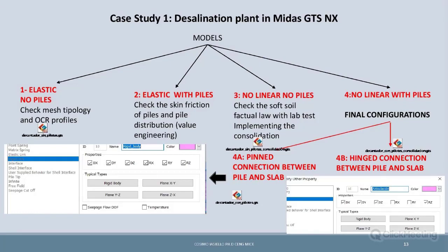Okay. Darius is asking me about hardening soil, modeling with piles. Yes, hardening soil. We are speaking about soft soil, and it is exactly the reverse. Hardening is where you have an increment of the resistance of the soil with depth. For example, hardening soil is widely used in the UK, in London, for London Clay or the Lambeth Group. But in this case, we are using soft soil.